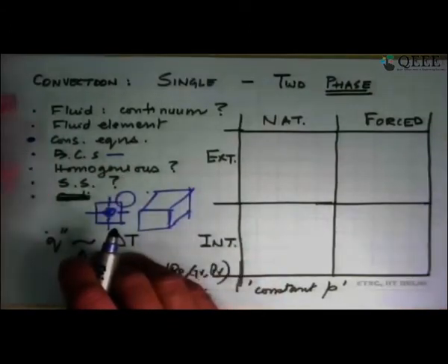And finally, all the things that we looked at in convection heat transfer, we said they were in steady state. Even though turbulence is inherently unstable, we still said that if you take a long time average, you would still see an average behavior, which is why we drew those velocity profiles inside the tube or the boundary layer profiles for turbulent flow. So we made that into a sort of a quasi steady state situation and said, look, those are time invariant things that happen in single phase flow.